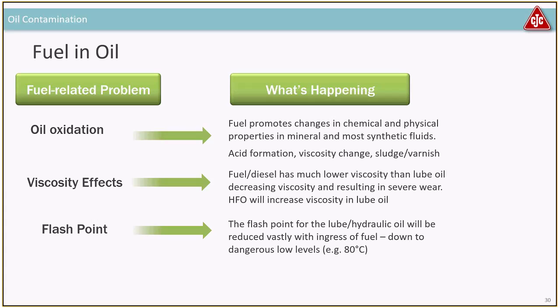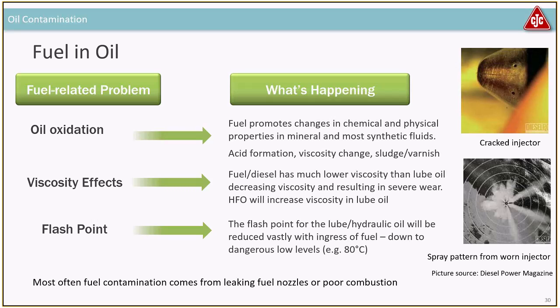In fact, it can get so dangerously low that you can have a fire in the engine, and that's of course not good in the engine sump. It could be from a leaking fuel pump, or a nozzle, or like you see here, a cracked injector, or the needle valve in a common rail diesel engine can also be leaking fuel into the engine. Or like this one shows a poor spray pattern, where you're not atomizing the fuel, but more like sending a flow of fuel into the combustion chamber.